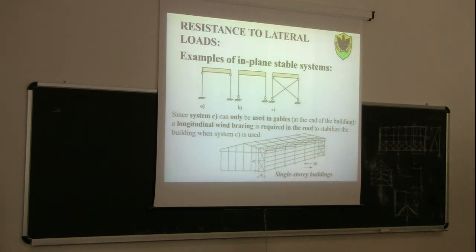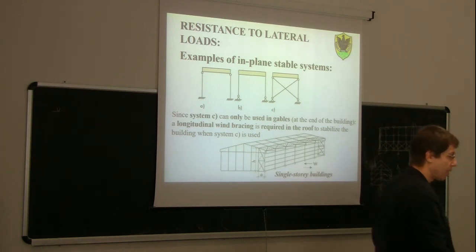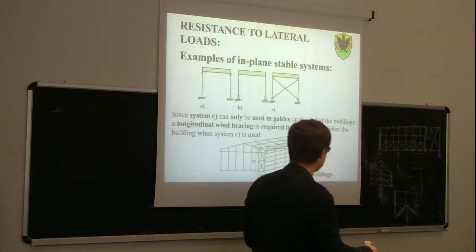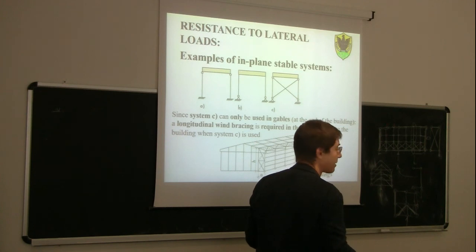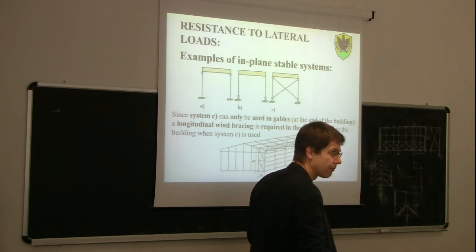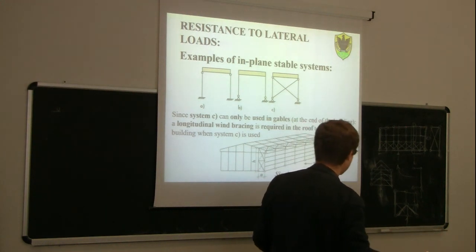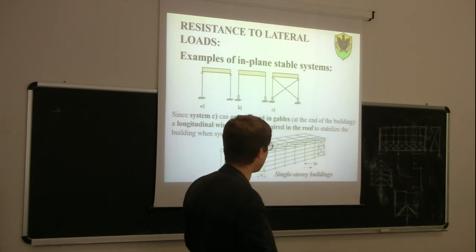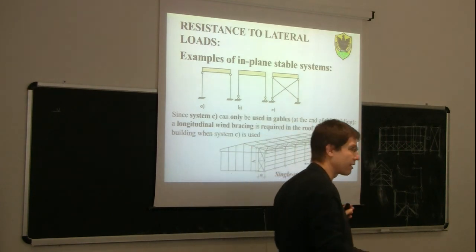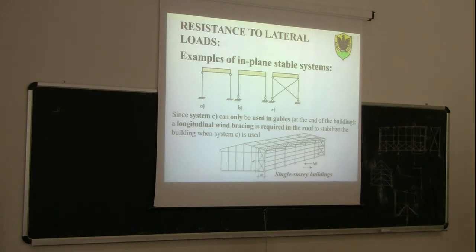Conversely, if I use, like before, a frame which is 2 or 3 mm, if all of those frames are stable, then I don't need this in-plane bracing system, okay? Because they are all stable, so the force will be transferred directly. But if only the frames at the two ends are stable, I need to put in this in-plane bracing. Is that clear? This is a very important concept. It's not like reinforced concrete, where we just give small information that we then don't use anymore. In this course, this information is very important, so you need to understand it very well.